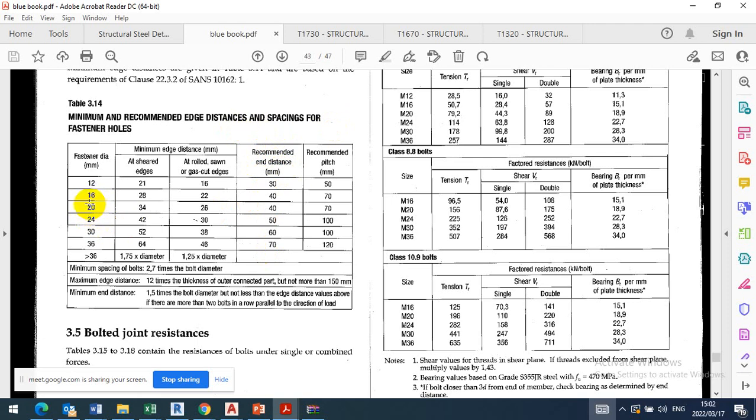Something that's bothered me: normally when they say the bolt size is 20, and then you drill a hole, you normally make it 2 millimeters bigger, 22. Yes, it's going to be bigger, to accommodate for threads and all that. So it's a 20 drilled hole. Then if we put the threads, it's going to go to 22, because you have to do tapping, thread making inside.